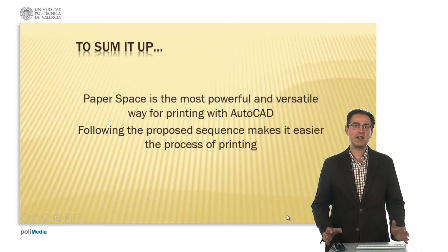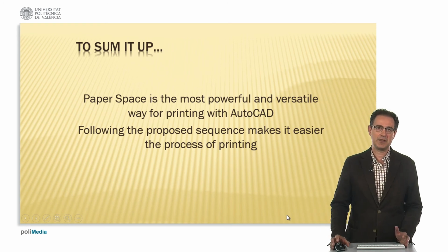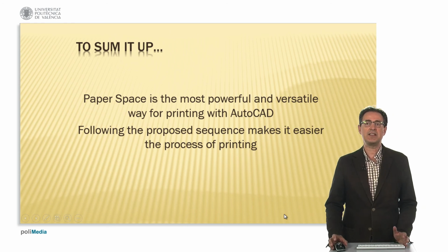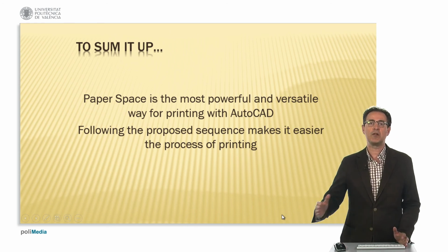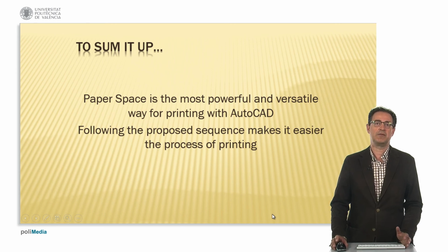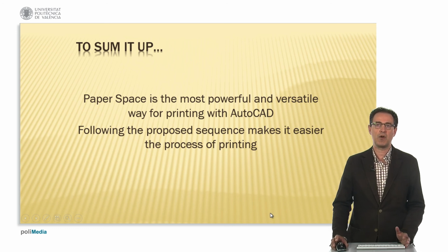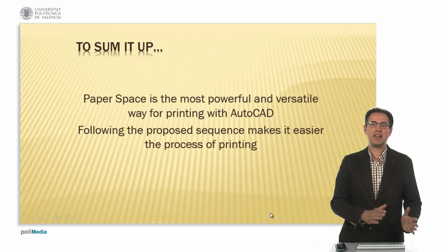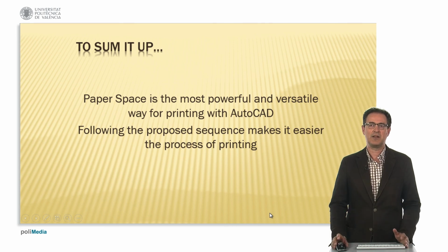So summing up the video, with this sequence it's easier to develop all the process of printing with AutoCAD. And as a conclusion, we could say that the paper space is the most powerful and versatile way of printing with the program AutoCAD, compared to printing from the model space, which is a bit old-fashioned.